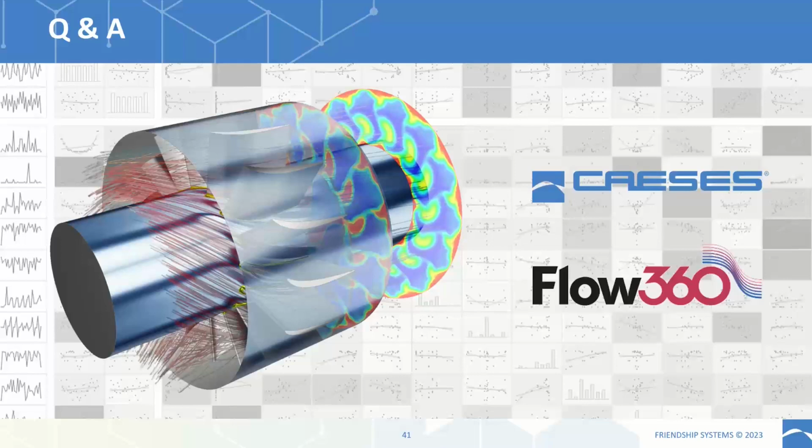And the multi-objective genetic optimization was performed on the surrogate model, and then we only do additional CFD computations in a very limited amount, and those are the ones that are shown. So when we get an optimum, it's computed, and then we feed that CFD data into the database as well, refine it, and so on. This is the explanation of what happened in these optimization rounds.